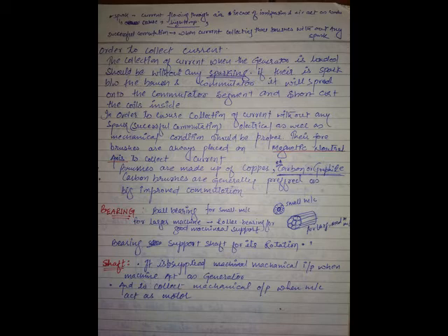So practically there are not 4 turns, there are many turns. I am representing it like this. So these are bunched together, strapped together. This is one coil side. Now, this coil side is placed in one slot, and the next coil side of the coil will be placed in the other slot. The distance between these two coil sides is known as the coil span.